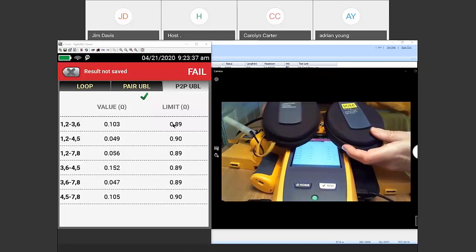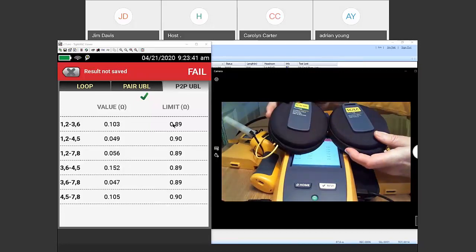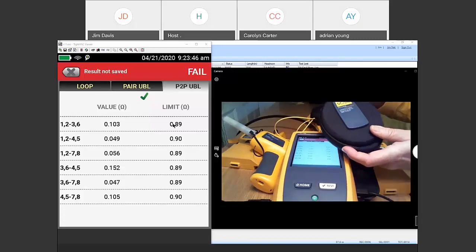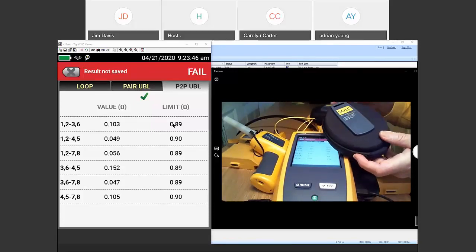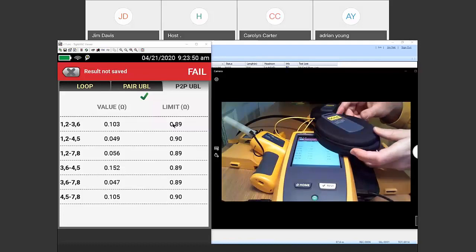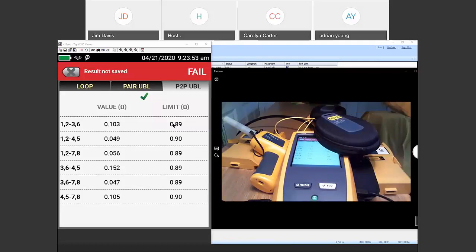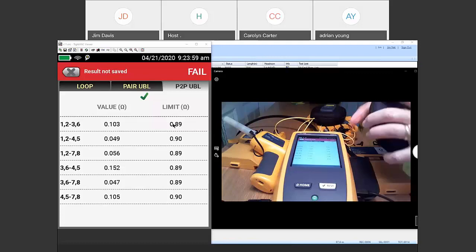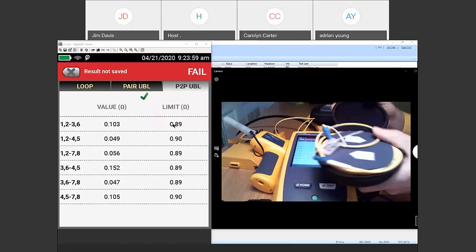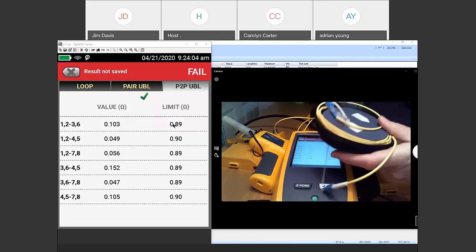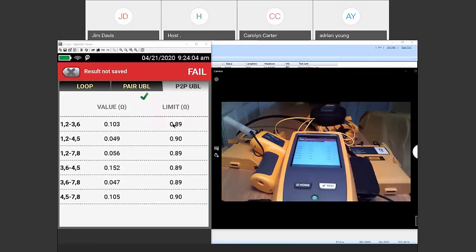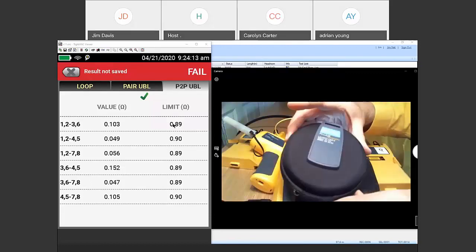Here we have an SC to SC APC. Here we have an SC to LC. So if you have an LC port on the wall, you're going to need LC on your launch pack. We don't want to put a short patch cord on the end of it. While this looks like a tiny piece of fiber inside of here, this is actually 160 meters. And our multi-mode launch pack, conveniently right here, has 100 meters of fiber in it.